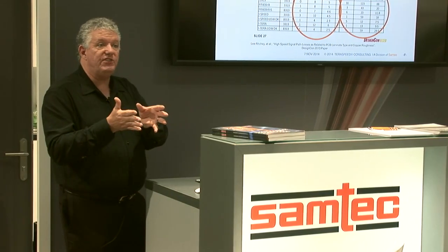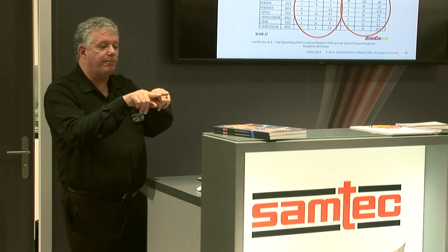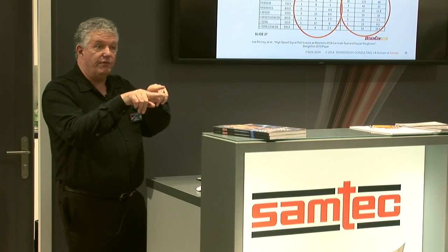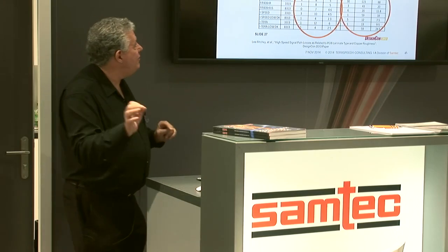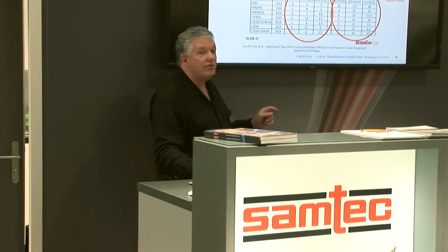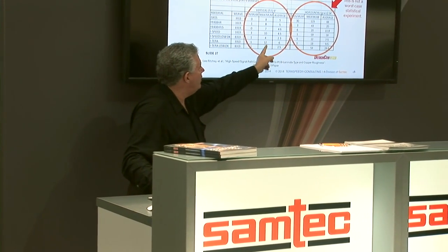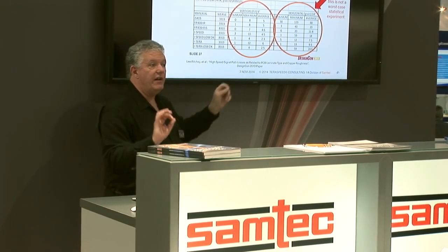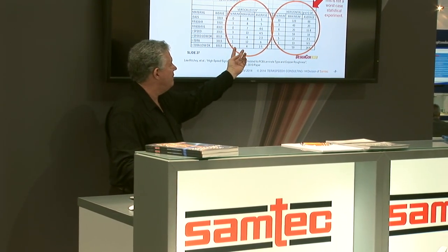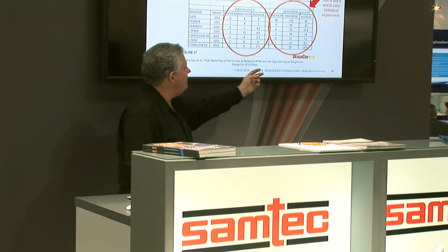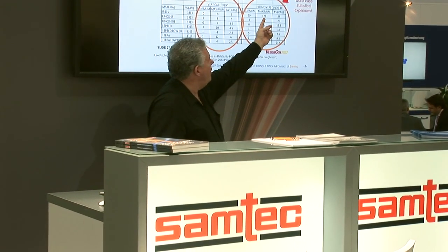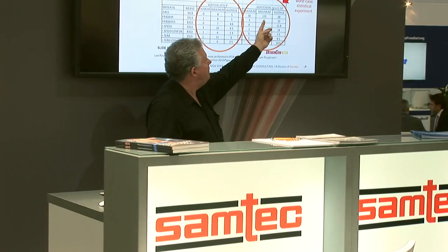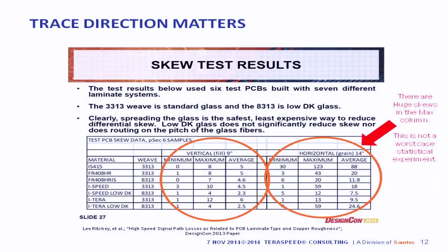We expect there to be skew because the average dielectric properties between two different traces can be different depending on where they are in the fiber, and we do measure skew. But something interesting happens. We measure fairly low skew on a 9-inch trace in one direction, and we measure fairly large skews, in fact, extraordinarily large skews, up to 123 picoseconds in 14 inches.